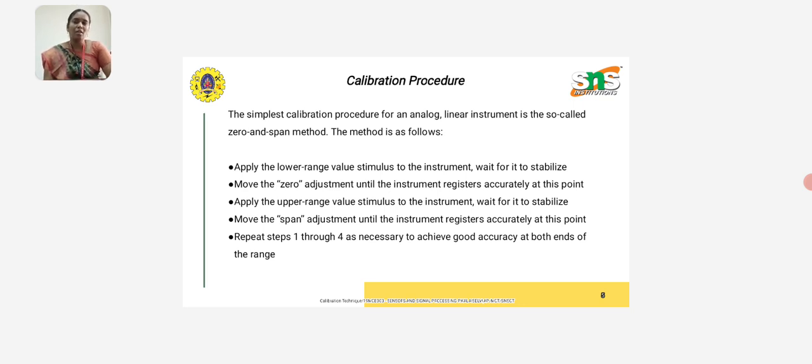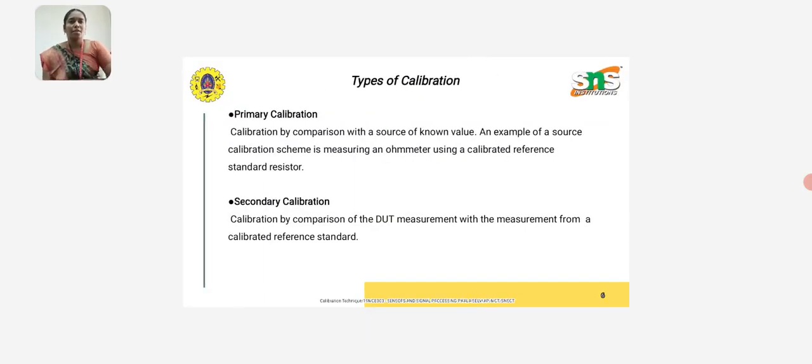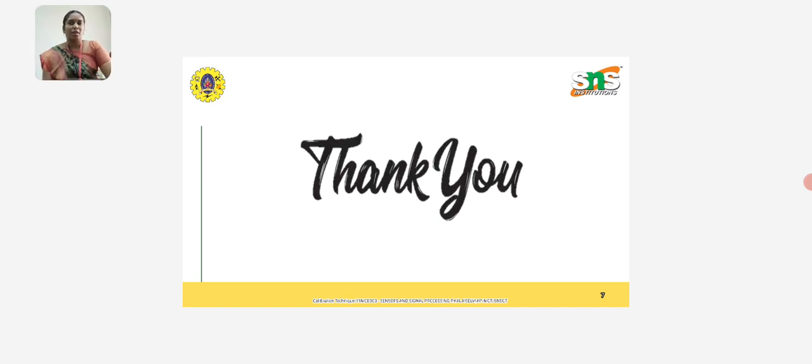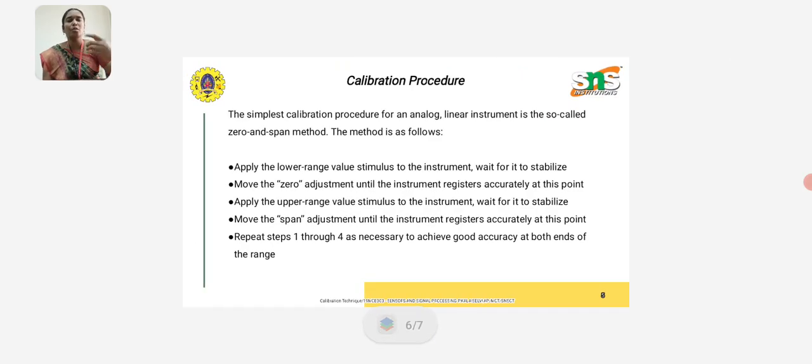And then the instrument is to be calibrated with values in both ascending and descending order. In a mechanical or electrical device, this procedure helps to reveal errors due to friction, hysteresis or similar phenomena. The standard used should be at least an order more accurate and of better resolution than the device. So while calibrating, it is customary to take readings in both ascending and descending order.